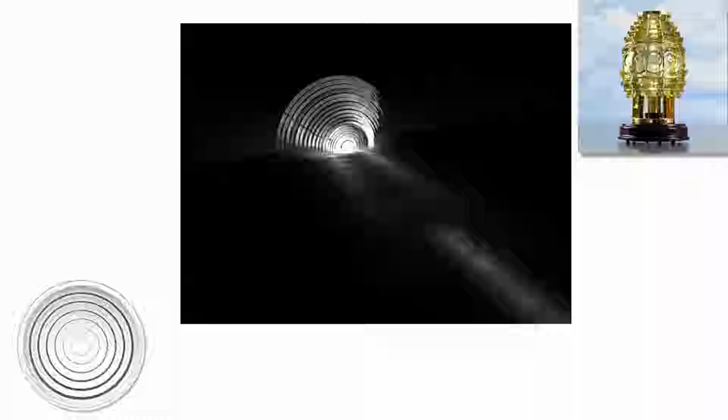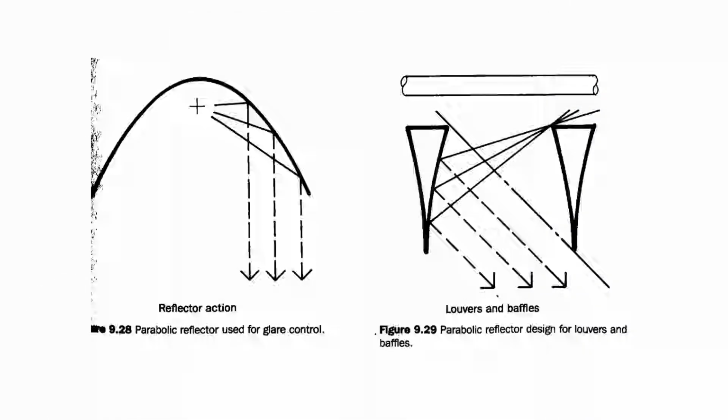And in fact, these Fresnel lenses were popular, particularly in downlights, when we didn't have quite as much industrial expertise to get light source luminaires that had better light distribution. You just used a glass lens to spread the light out. Now, when we got that industrial ability, we were able to produce parabolic reflectors.